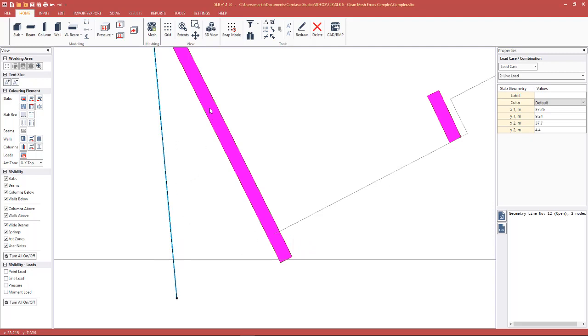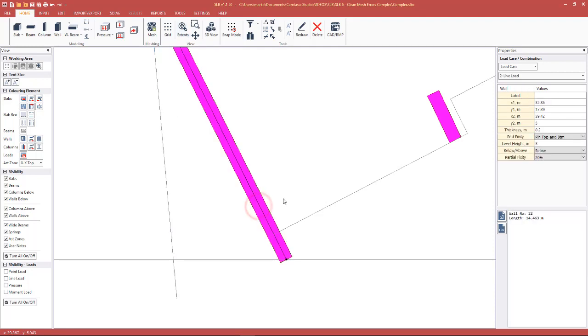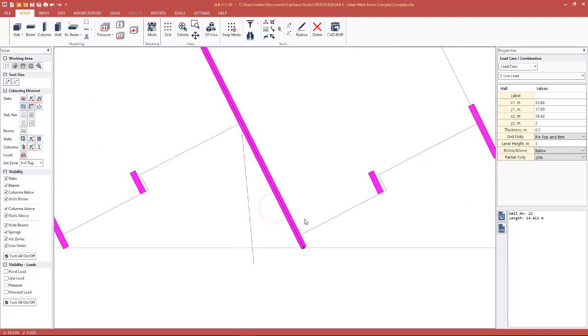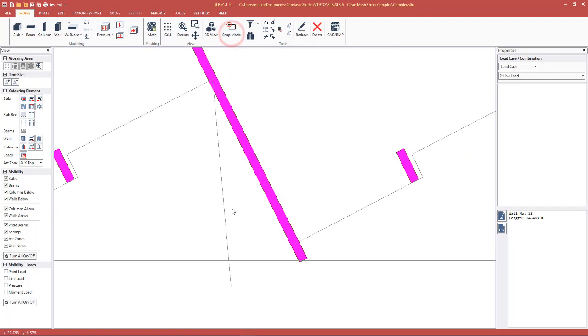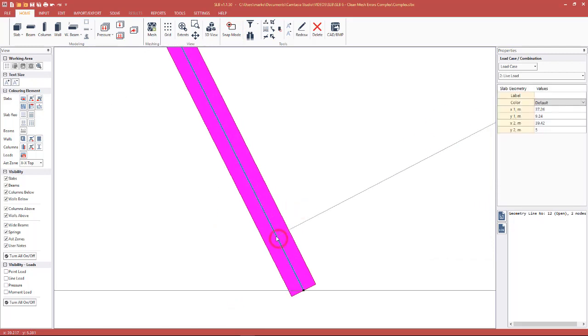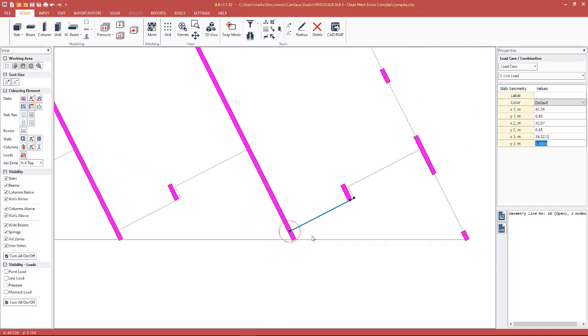So we already knew from the very fact that there were meshing errors that there was a slight difference in the angle between the geometry line when it was sitting on the wall and the wall itself. But now we ensured that we clipped this perpendicular geometry line to the wall center, which we are using as the reference. Change snap settings to snap to corner. We simply snap this geometry line edge back to that location. Now there is no need to put a node in here because we've already got this high degree of accuracy from the extend with mouse and clip operation.